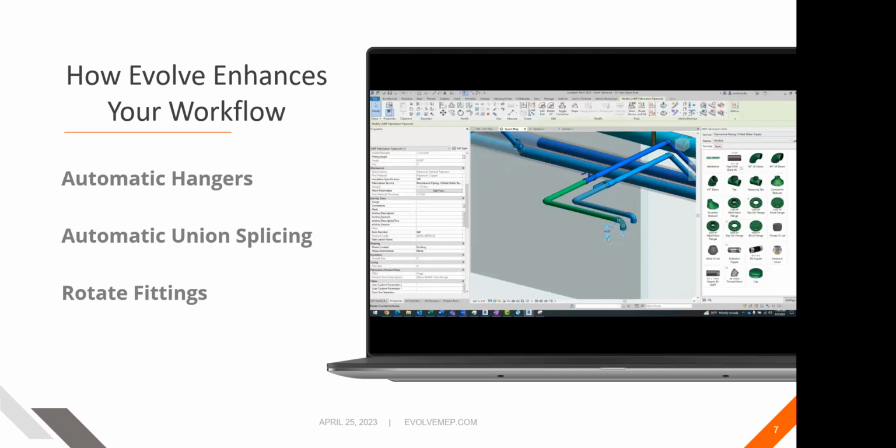There's things like that that decrease your drawing time. That's why contractors are going to use Revit over CAD, because of the level of detail you get down for fabrication, to make sure you guys are not clashing with each other's services. Biggest takeaway with Revit is also the information that comes with modeling, especially if you're modeling, again, with fabrication parts. 3D visualization, all that stuff, yep.